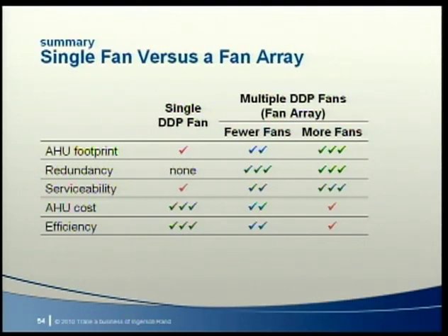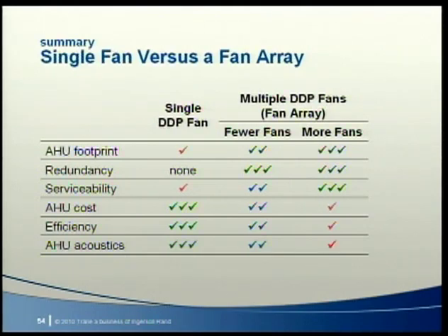Using a single fan will typically require less power than an array with multiple fans. When a fan array is desired, using fewer, larger fans will typically require less power than using many smaller fans. In many cases, the fewer the number of the fans, the better the acoustics. Fewer moving parts and therefore fewer fans generally results in better reliability. Of course, the redundancy provided by using multiple fans partially offsets the concern over a fan failing.